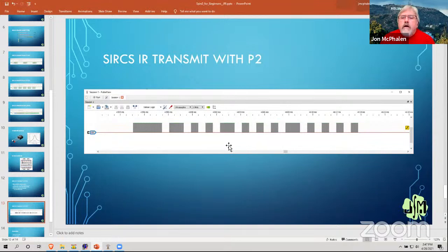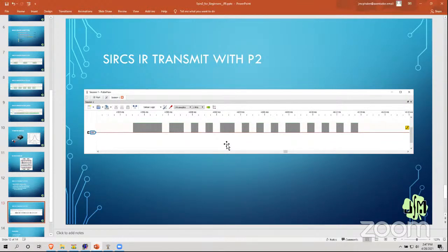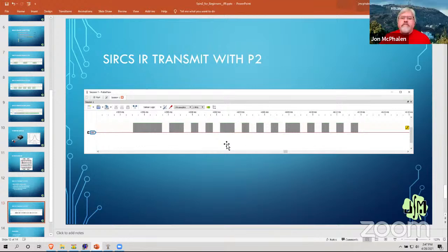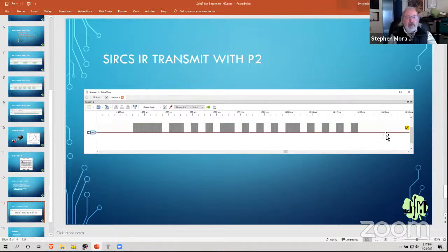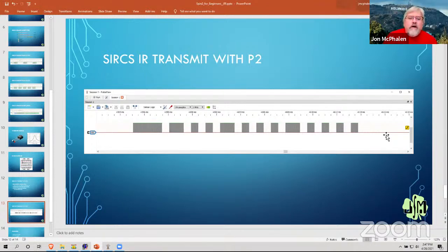So which one of you clever people wants another ice cream from Ken can tell me what key generated this code? That'll give me time to open up another can of water. It looked to me like an 8. Am I right? Or is that a 0? It's a 0, because you can see 1, 0, 0, 1. So this is 9, but remember, it's off by 1, and this is a TV remote. Here's 1, 0, 0, 0, 0. I will forever be amused that 0 is 9 and 1 is 0, etc.